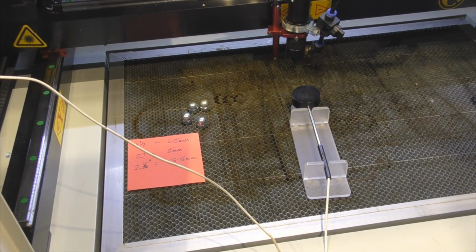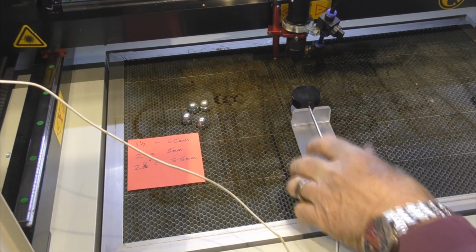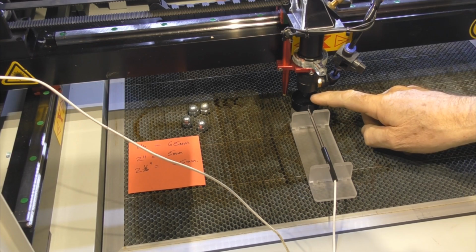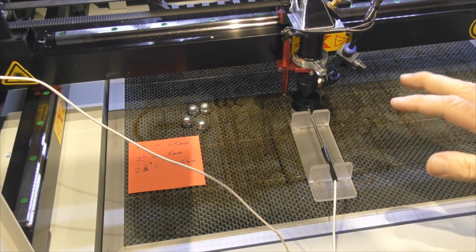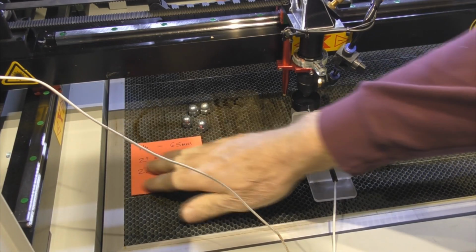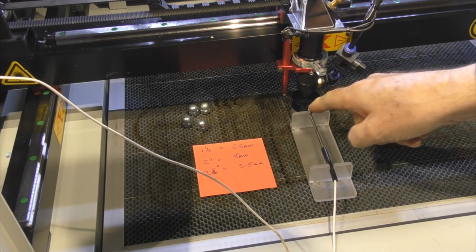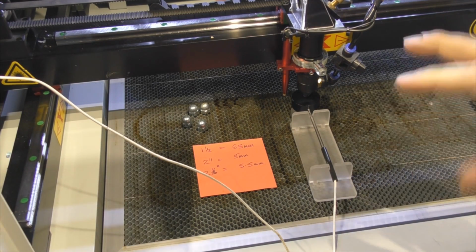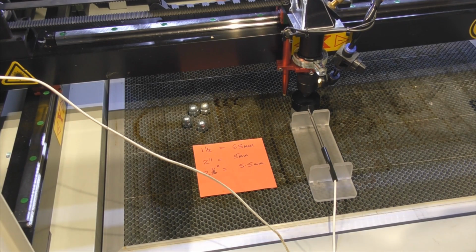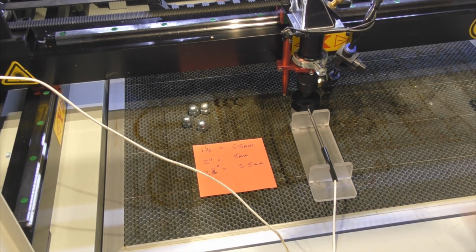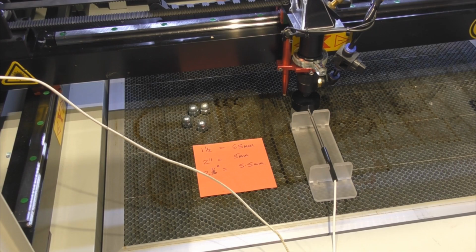They're going to move the head to a position on the centre of this target here. Because the beam is focused through the lens, if we drop that down to just 5 millimeters, which is the focal point, it will do a nice engraving job on the surface of that black aluminium. Now that's anodized aluminium, which is 100% absorptive to the rays of heat energy that come out of here. Natural aluminium is reflective, anodized aluminium is 100% absorptive. We've got to drop this down about 2 inches.